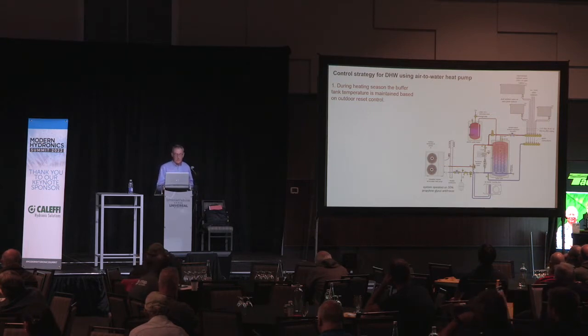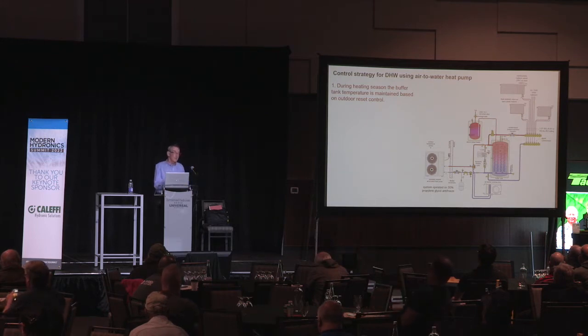So the electric boiler would operate, again, as supplemental heat generation to the heat pump. It would also operate, if it needed to, as either partial or full backup. It would depend on how you size that electric boiler. And by the way, when you size up an electric boiler, if you're going to do whole house space heating with it, make sure you include the cost of the electrical cable and fittings back to the breaker panel, because those costs are very high today, and make sure you've got at least a 200 amp breaker panel. All right? You're going to need it. They draw a lot of power.